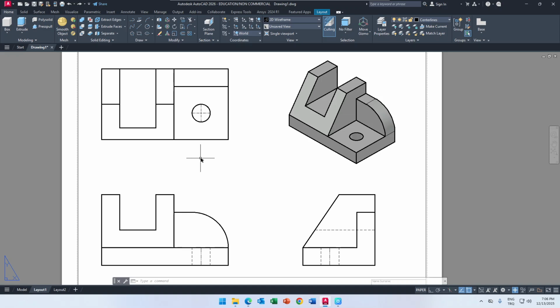And one more thing is the most important one. You shouldn't add one more dimension if it is apparent already. What I mean, look at here, this dimension, if I add here somewhere, it is already known, right? So I have applied one and show that one. So I should not add that dimension here again.